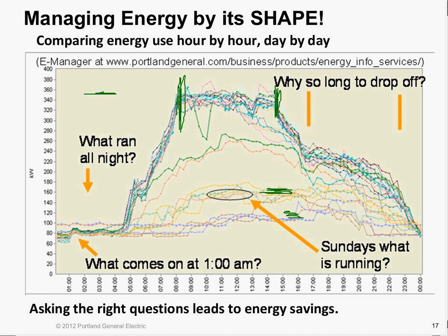And you can ask some very smart questions without knowing any formulas or anything about energy. You can say, gee, something came on every single night and stayed on. Every single night. It comes on and it stays on. You have this definite shape over here. I heard they finally asked enough questions that the IT department said, oh, that's us. We have some software that turns on every computer in the school and backs up the data on it so that we have backups of all our data. But the software is not smart enough to turn the machines off. It only takes about an hour.